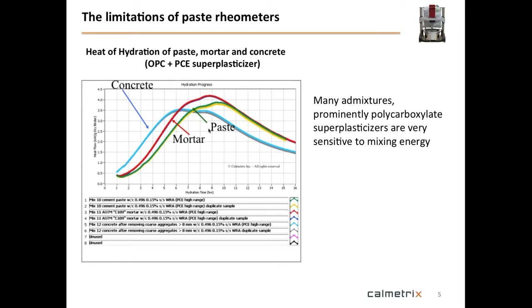There are concrete rheometers out there. Indeed, there are rheometers that were designed to be used for concrete. And notably, I can mention a few. There's the Rheocad, there's the Viscomat, there's the contact rheometers that come from Iceland that are designed by people that are very knowledgeable in rheology in general, and especially in the space of concrete. And there's the ICAR, like a field test rheometer. So all of those exist, and yet they also lack certain of the design characteristics that you would want to see in a concrete rheometer. So you can indeed test concrete in there and not paste. However, these suffer from something else.